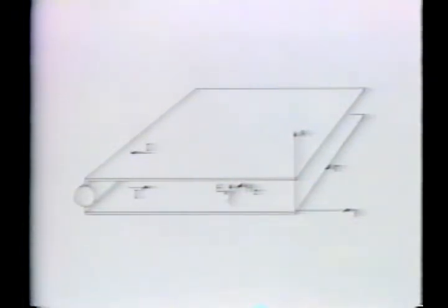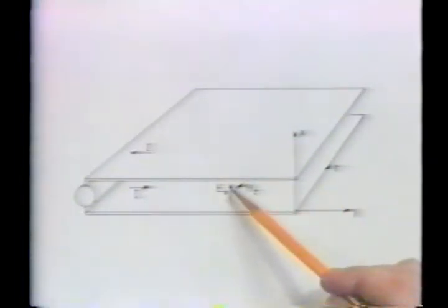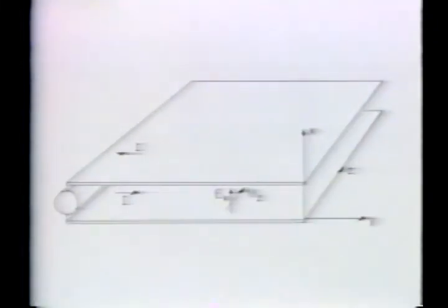Terminating in positive and negative axial surface currents on the conductor surfaces. Both E and H are perpendicular to the direction of propagation. We therefore have a transverse electromagnetic wave. Such TEM waves can propagate on pairs of conductors of arbitrary shape, so we needn't be concerned with the width of the plates relative to the spacing.